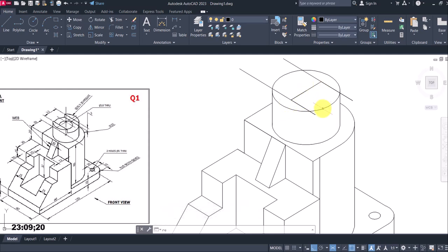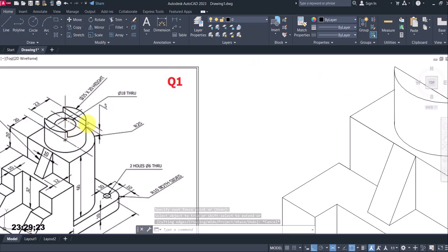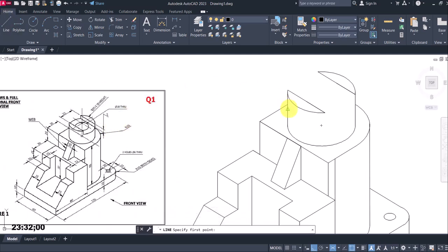Now I can trim. I'm trimming with my shortcuts. It's my AutoCAD shortcuts. Okay. All right. Then this line also can go. These two can go too. From here, now I can continue. The depth of this cut is 5. So I can do 5 downwards. F5. Distance of 5.